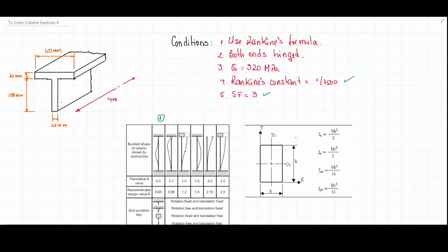Hence, the buckling load is going to be different according to the ending of that column. And as I'm already working ahead, I know that this section here is a little bit custom, meaning that there might be nothing commercially available, because there is nothing being said anywhere about this or with manufacturers, they're only giving me the shape of it. Then I might need some help to calculate the moment of inertia of this beam, as I know that in my column formulation I would need the inertia of that column. So I have it here.